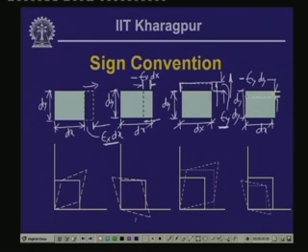Now, in case of shearing strain, as we said, when the angle decreases, it is positive. This was the position x and y, and from this position, this was the element dx and dy. Here it is oriented in this form, so the angle which was 90 degrees before is now reduced, and hence this shearing strain is called positive shear strain. Here in an anti-clockwise direction it is moving in this form, and here in a clockwise direction it is moving in this position, and we call this gamma xy by 2 and gamma xy by 2.